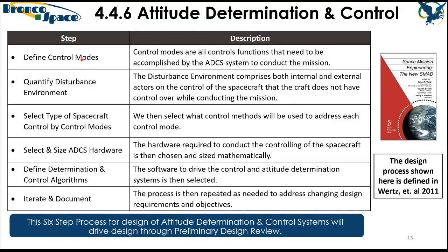One thing you do need to remember is that the magnetic disturbance environment is oftentimes the worst one for CubeSats, especially if you have anything that's magnetized or magnetorquers on your spacecraft. There are known cases where magnetic disturbances have thrown CubeSats really out of whack. One famous example that I always bring up is the MOVE-II spacecraft from the Technical University of Munich. They had a wiring issue that they did not know about before they launched. Essentially, the wire that came from their solar panels into the spacecraft created a loop.